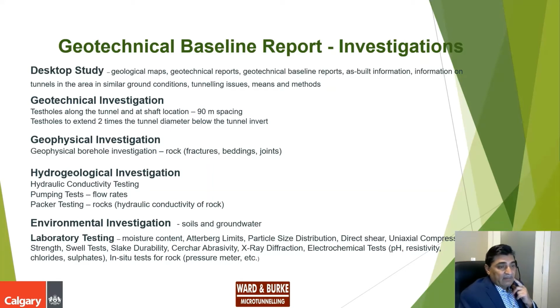Uniaxial compressive strength. Normally we do it for rock. Swell test for claystone. Slake durability for claystone. Cerchar abrasivity for sandstone and boulders. X-ray diffraction for claystone, and electrochemical tests for soils and bedrock to see what is their pH, resistivity, chlorides, and sulfates. Sometimes we do in situ tests for rock as well, such as pressuremeter.